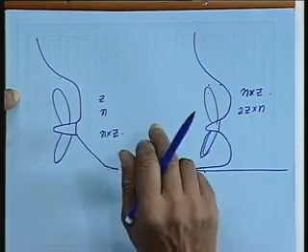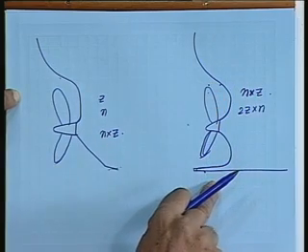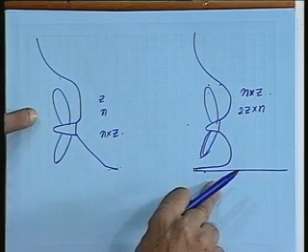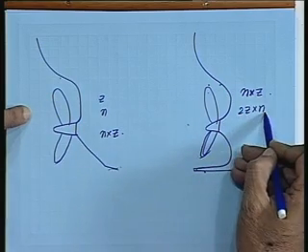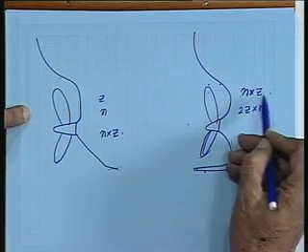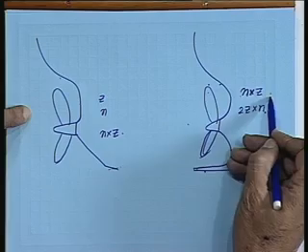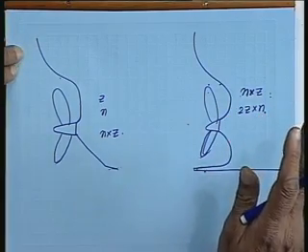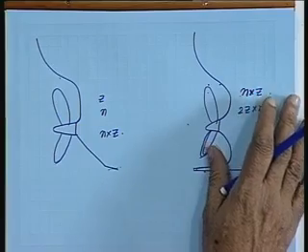So in one revolution, 3 times on this side and 3 times on this side, so 6 times it will be generating the frequency. So 6 times the frequency here, and if it is an even number, then number of blades times the frequency. So these two possibilities are there.